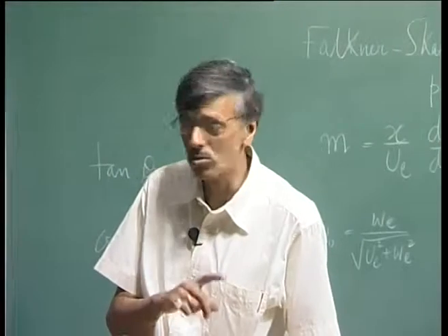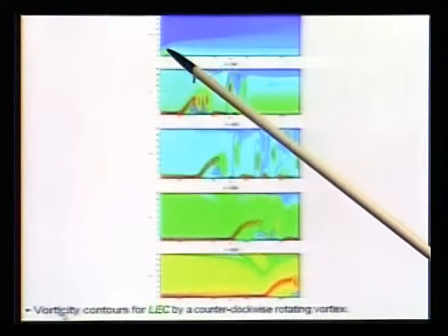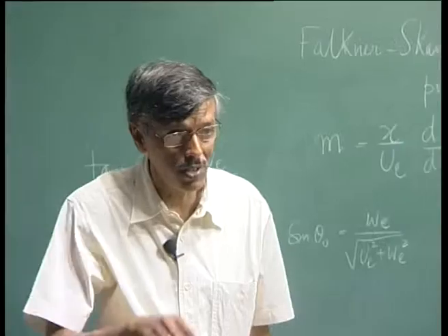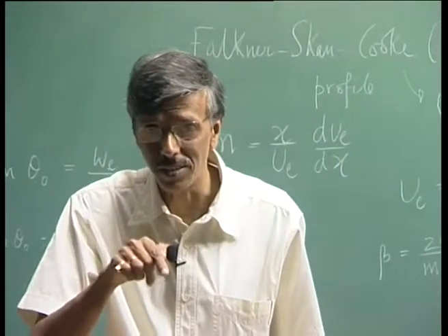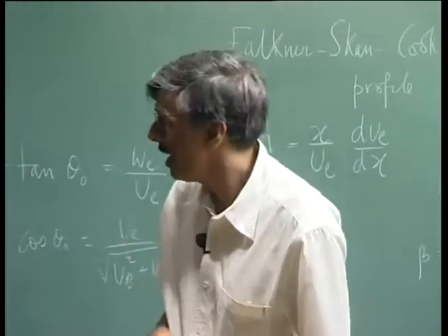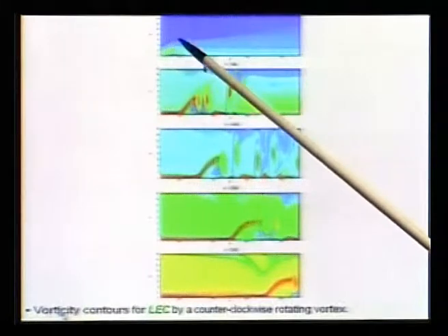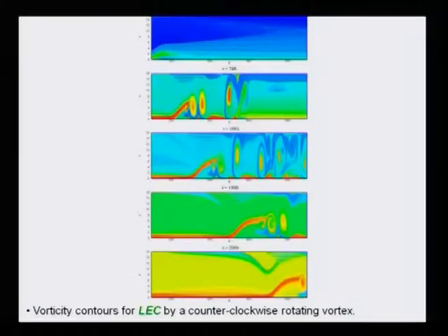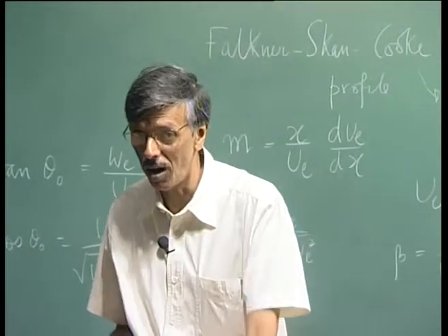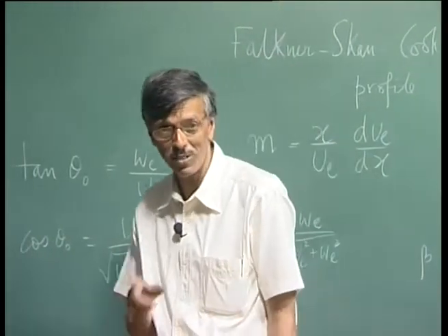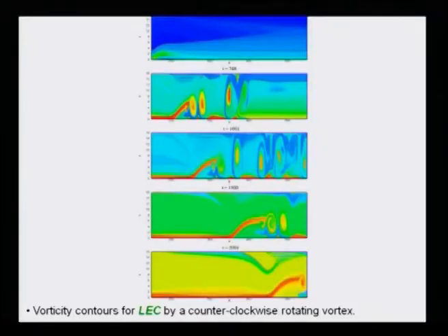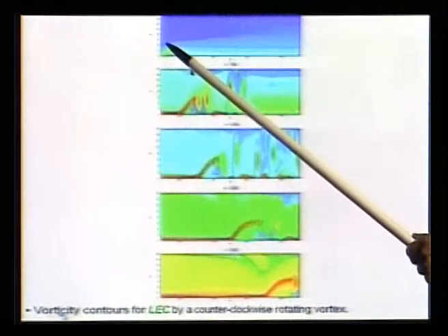Of course, it does so through the inflow boundary condition. At the top of the computational boundary you have some imposed condition that shows the effect of the approaching vortex, and you can already see a bulge there indicating the flow is being affected. And that answers your question whether we have a constant shear layer thickness or not. It just simply starts affecting it somewhere here.